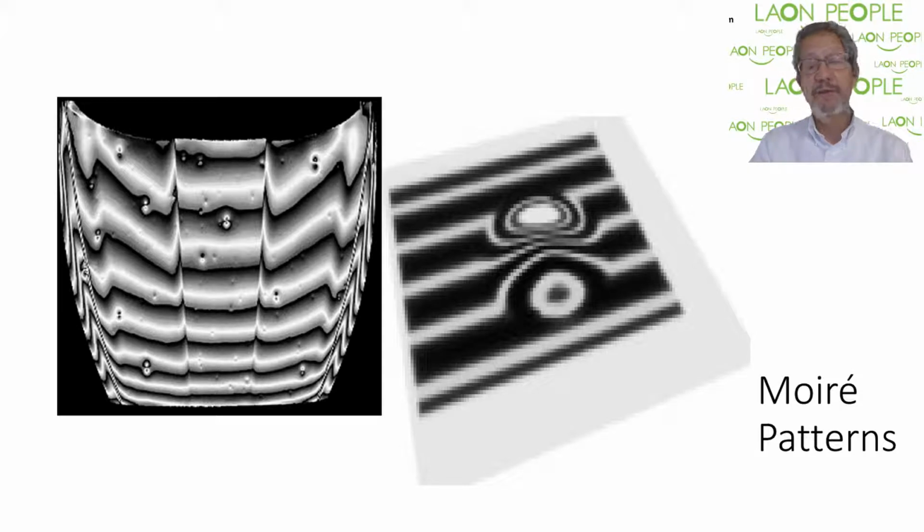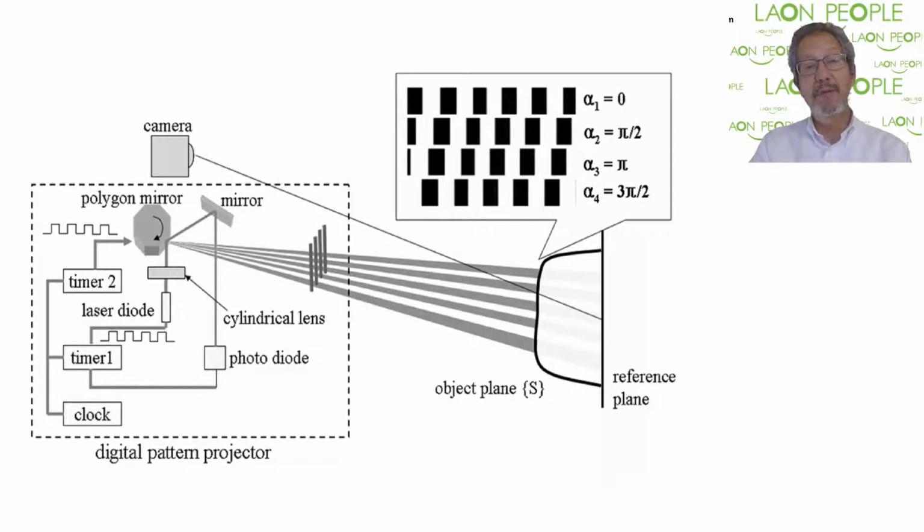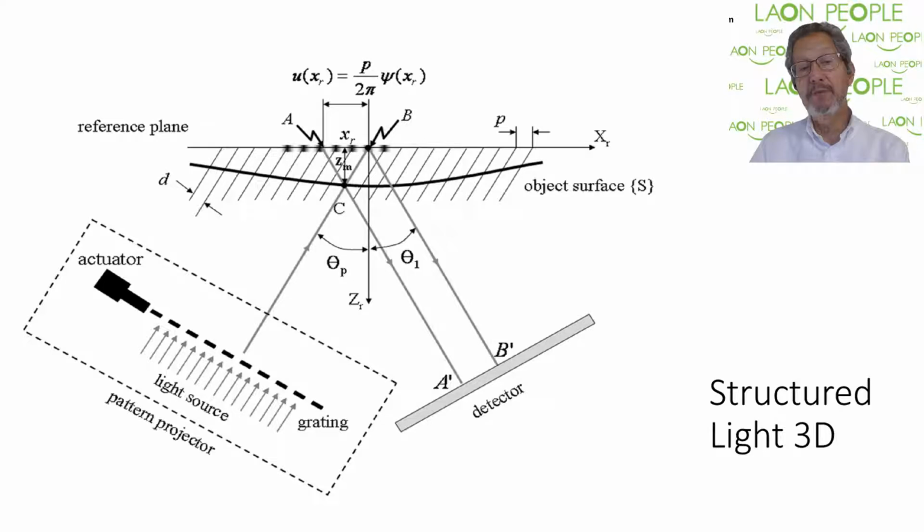Now sometimes you have other types of problems, such as a very shallow dent. It's very hard to see, and so what we actually did was we used the light field that we have and did a structured light 3D assignment on it. It's like an ellipsometry process where you can actually measure the depth of the surface relative to the fixed light source and the fixed detector.